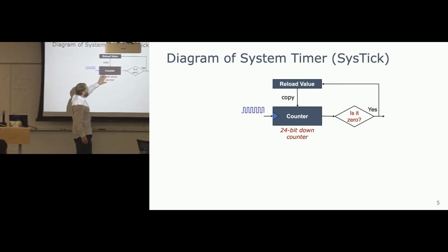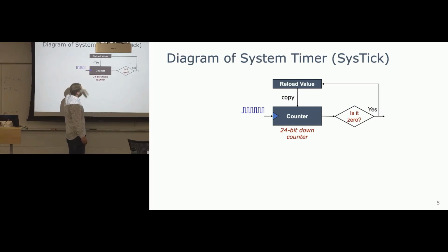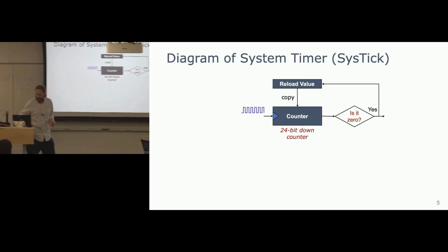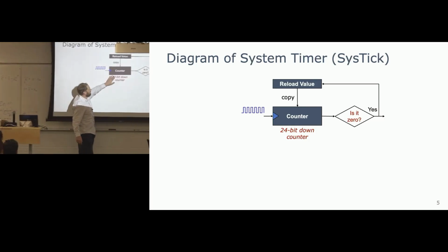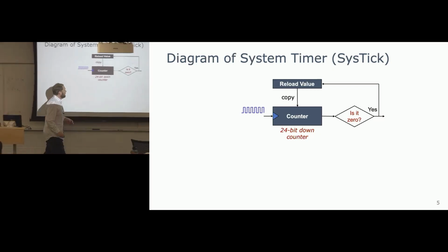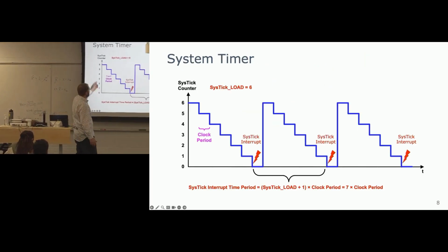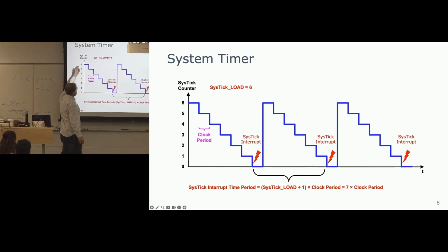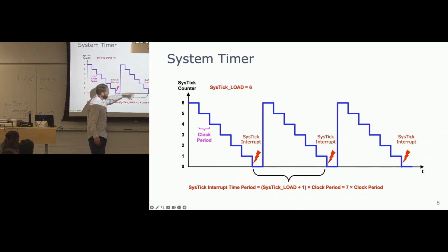It's not a 16-bit timer, it's a 24-bit timer, and basically there's a reload value, and it's just going to be counting down. That's all it ever does, and then when the count transitions from 1 to 0, an interrupt can go off, causing an event to happen. Basically, as shown here, it's always a countdown. You set the auto reload timer, they just call it the reload timer, and it clocks down. You have a tick that goes off, and you do a task.